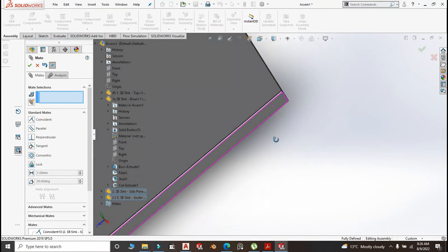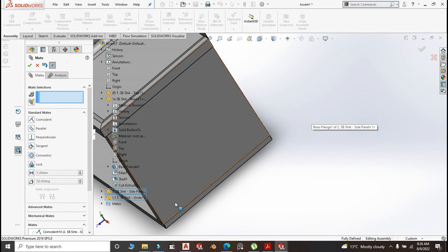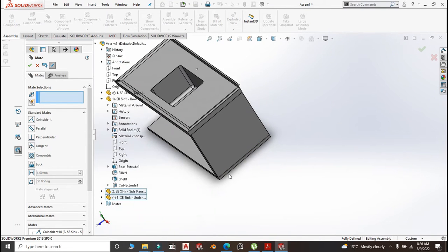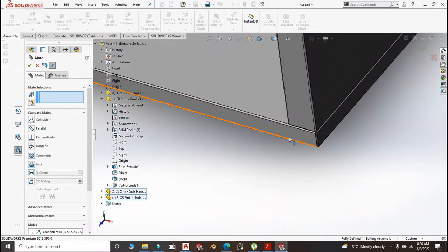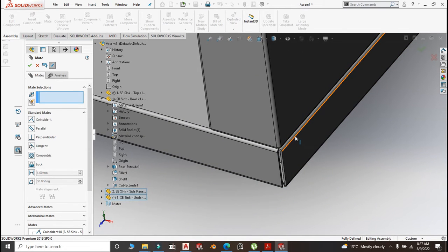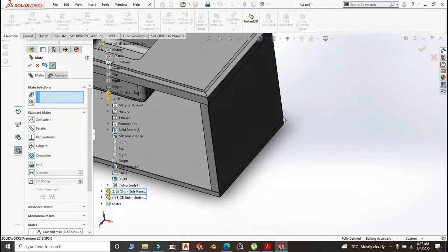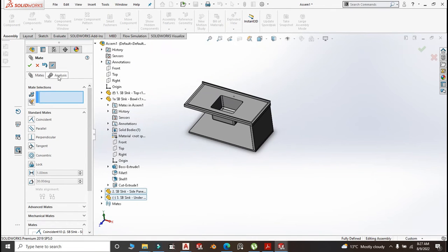Now you see, everywhere it is flushing. And for this, we don't do a lot of welding, because this is the face. Here you can do a full welding. Remember the undershelf, you will do a welding there. You can do a stitch weld here about 1 or 2 inch long. Same here, then a small tack weld someplace there.